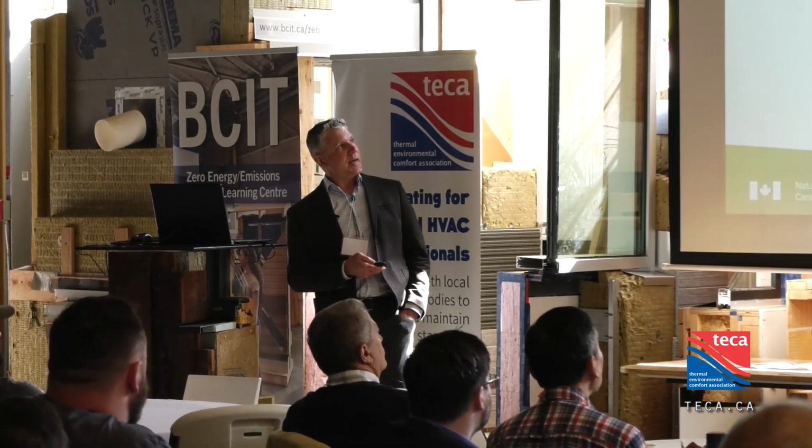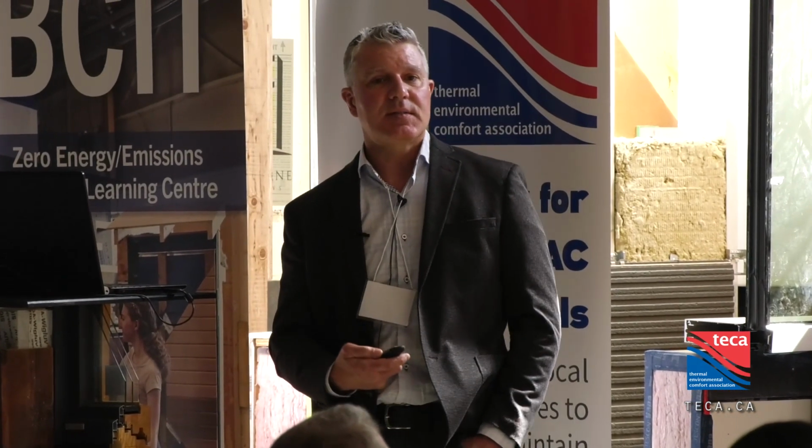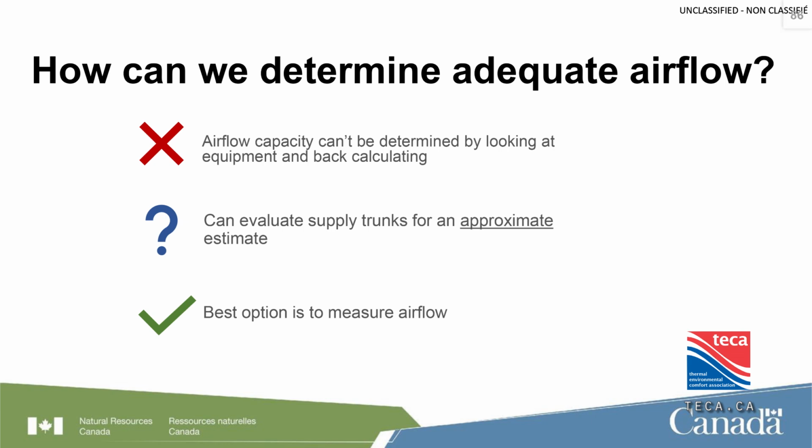So determining adequate airflow, it's really hard to do that by just looking at the system. We could actually do some measurements and see what it is, but even if we were to do that, the static pressure within the ducting system cannot be calculated by just taking measurements. The best option is to actually measure the airflow that's happening throughout the duct system.